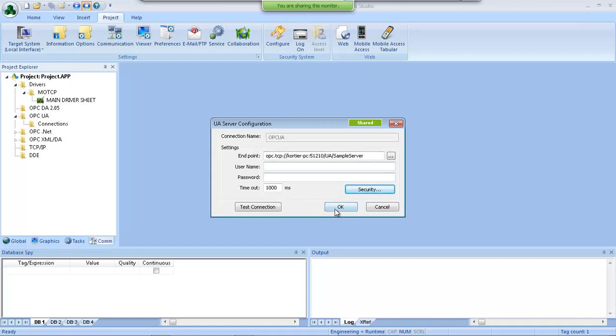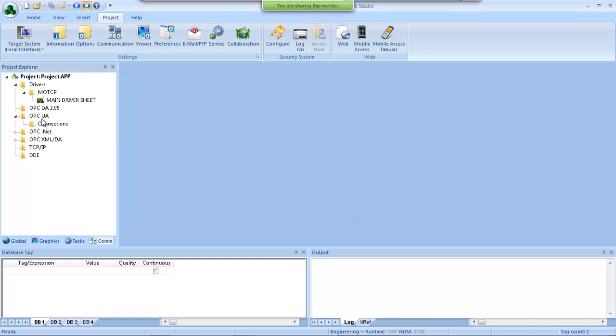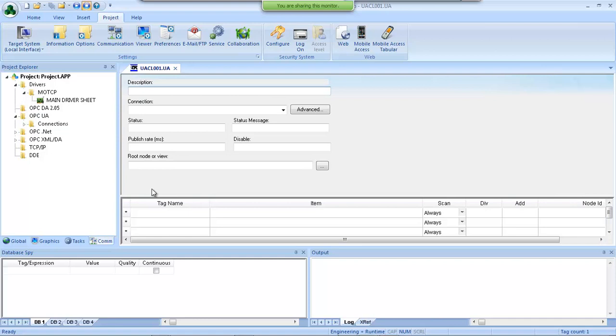So now that I have this named connection in here, what I can do is insert an OPC worksheet, and choose the connection that I'm going to use based on this name. The way we've done this adds flexibility, so as you create additional OPC worksheets, it lets you choose which connection you'd like to use. So if you have different OPC server connections to different controllers or different PLCs, that's a very nice flexible option for you.